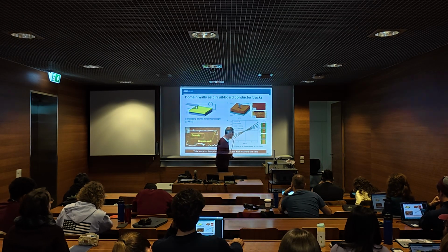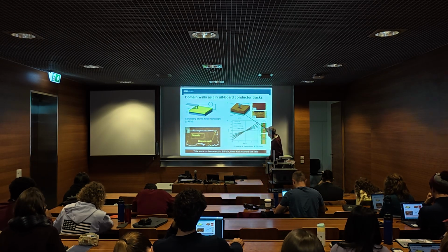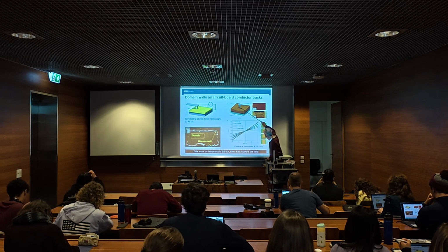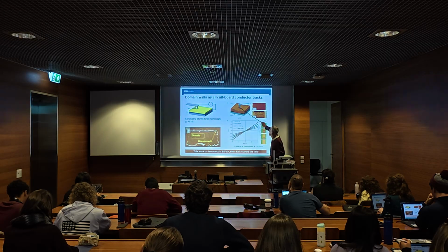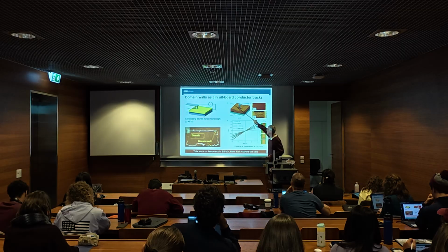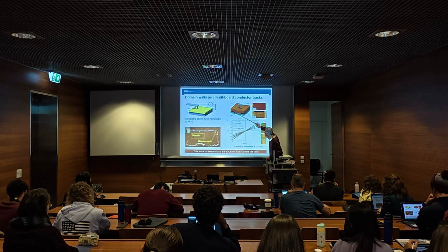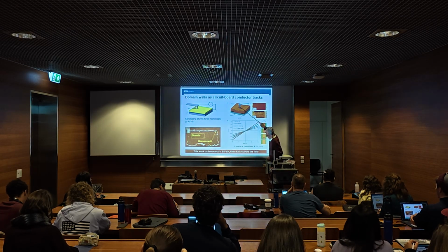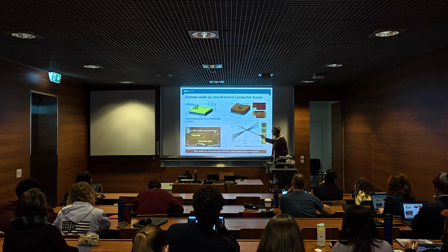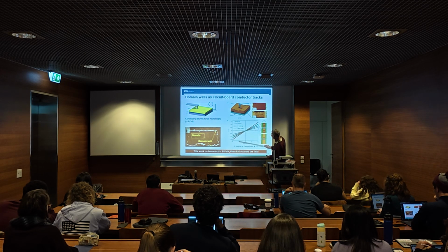They even made a conceptual demonstration of this wire principle. So they had two metallic plates here. Strontium ruthenate is metallic. And in between they have bismuth ferrite. And then they, with their voltage tip, with the voltage that they locally applied, they created an oppositely polarized bismuth ferrite domain. And that means they created two ferroelectric domain walls, going between the two electrodes, because this goes through the entire material. And then they could show that if you have zero of these wires, so you don't have this oppositely polarized domain, then you get this curve.